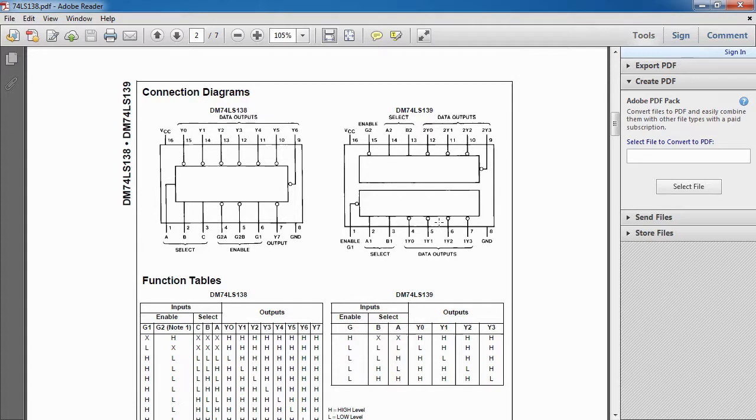Let's have a look at the pinout. Okay, so this is fairly common. We've got the ground and the VCC in opposite corners, as we've come to expect. We have 8 output lines. This one's slightly trickier than the last chip we looked at, in that we've got the first 7 lines here in nice numerical order, but then the 8th line, Y7, is over on the other side, but that's pretty easy to deal with.